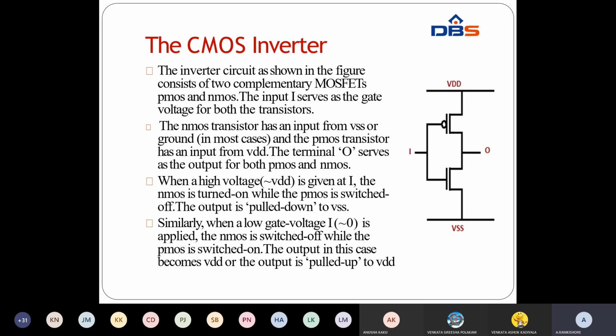But consider chips from different logic families: in a single circuit we connect an op amp, an operational amplifier, and another digital IC that came from a different logic family. That may not be compatible, and they may use different power supply voltages, or different input and output conditions to represent the logic value.